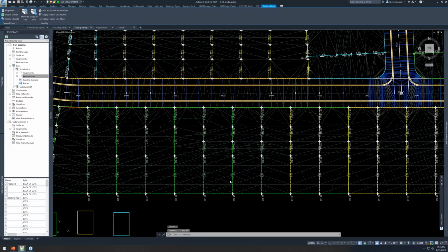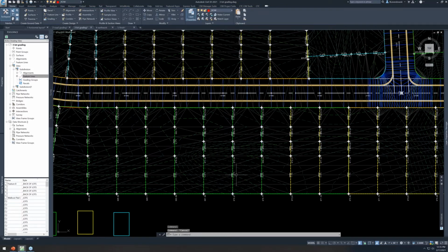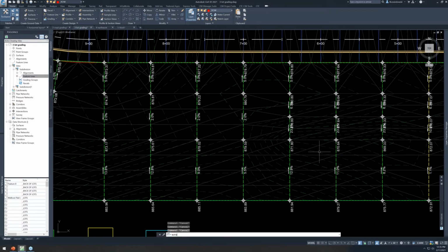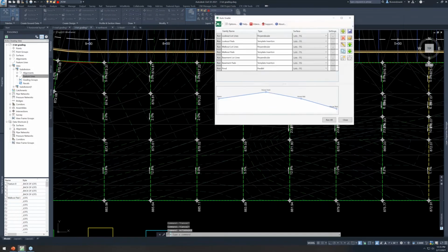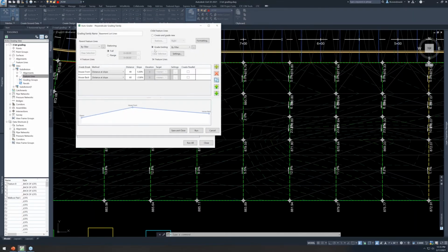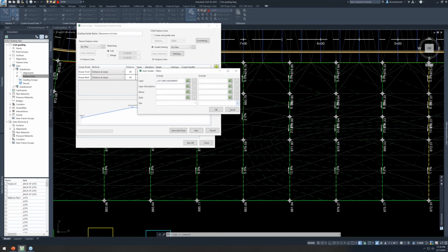Now when I do that, nothing happens to the geometry itself. I just change layers, okay? But now that set of feature lines is going to get caught in, guess what? The basement lot lines family. That's this one right here. This is a dynamic family. There isn't a finite set of feature lines. This said 51 before, now it says 54 because it found 3 more of them based on the layer filtering I have here, okay?